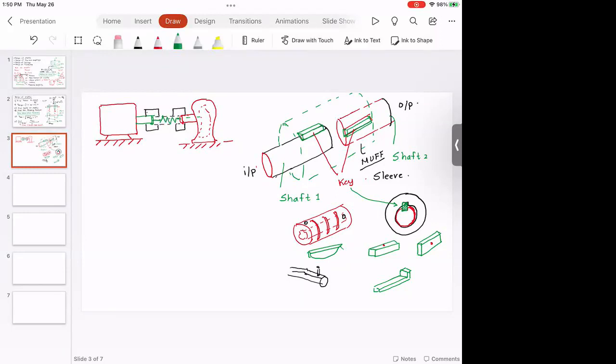So if you have a coupling like that, then you add springs. What is the advantage of springs? The spring would minimize the shocks. It absorbs the teeny tiny amount of shocks. And in the case of 3D printers, as you know, the stepper motor starts, stops, starts, stops, starts, stops. So basically, the teeny tiny vibrations from the stepper motor do not get transmitted to the lead screw, because that would affect the quality of the parts. So this coupling is an inexpensive way to compensate for misalignment and to compensate for shocks, vibrations, and jerks.